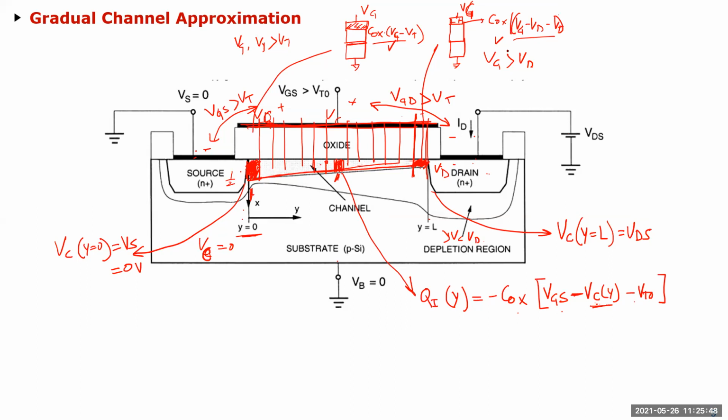The gate terminal is always VG, but the difference across the oxide is VG minus VD in one case and VG minus 0 in the other. So let me redraw this here. This is obviously ground, and you have a channel now, so this channel voltage here is also ground.